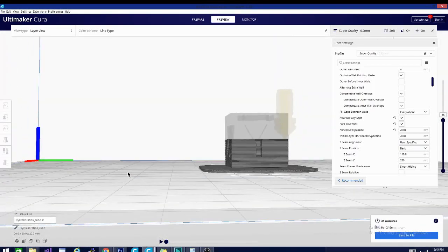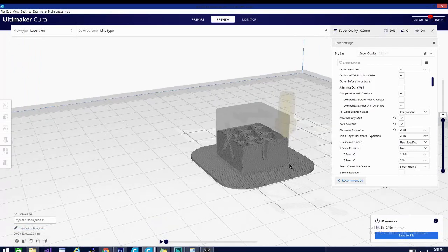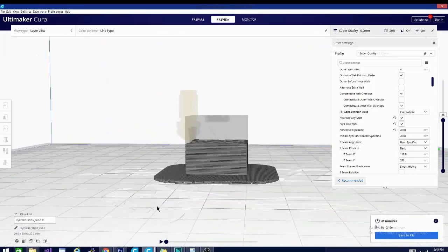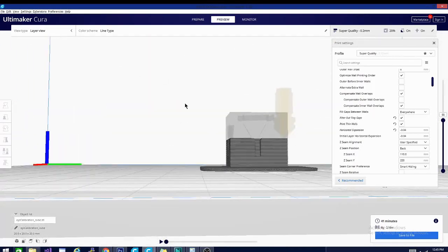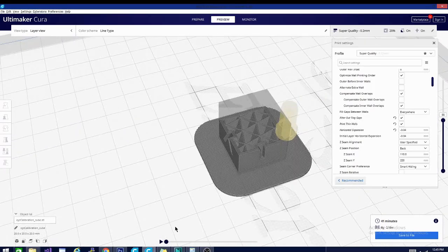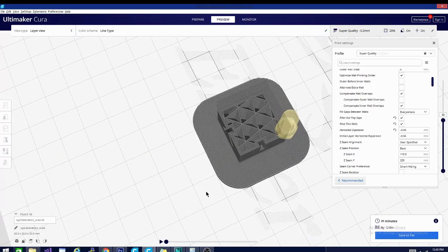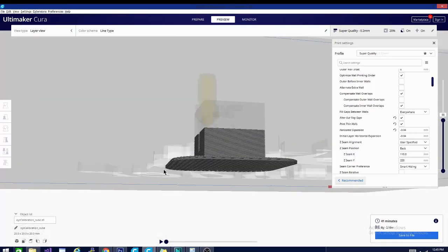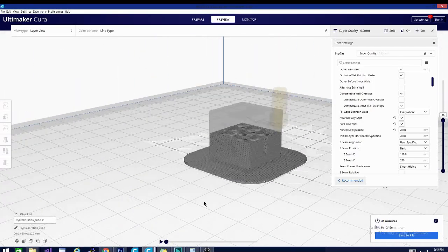So in this case, this is the setting that I would use because I'm making a cube and I want not only all the edges to be uniform, but at least this edge here to be uniform with itself, so it's easier to adjust to fit the others. If I need to post-process, do a little sanding, it all comes off of one spot here, right where this seam is. And in most cases, as long as the seam is on that sharpest corner and in one vertical line, not broken up randomly throughout the model, you don't really need to post-process it because you won't really see it unless you're specifically looking for it.